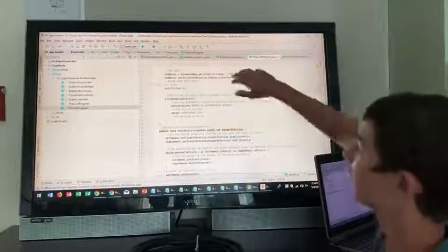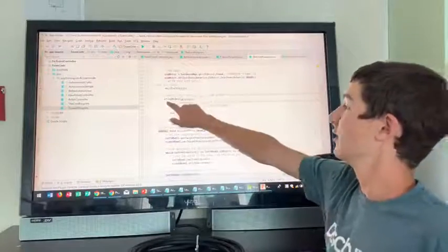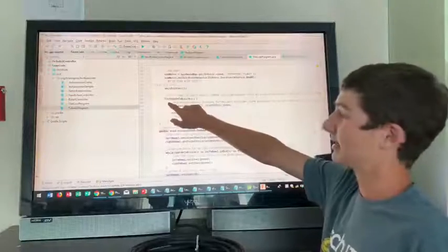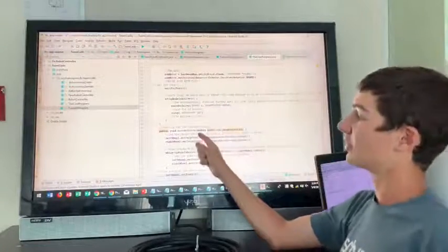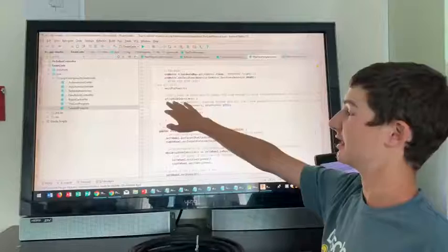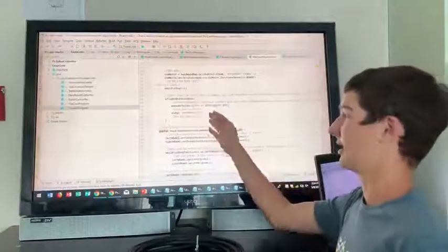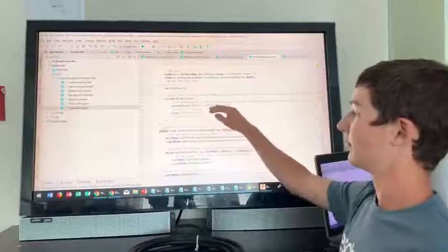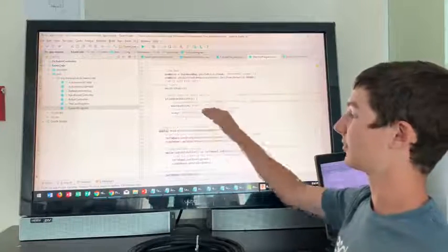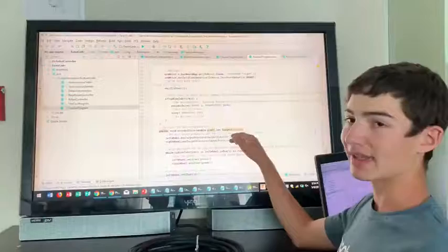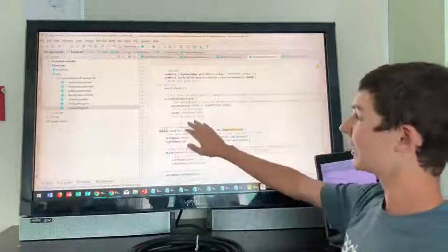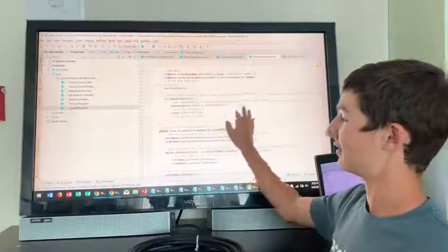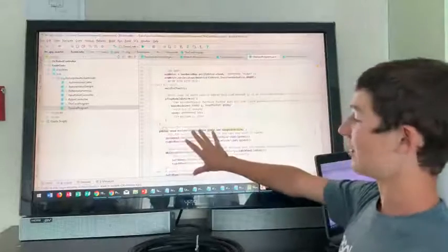And all the way down to our while loop. And actually, we don't have a while loop this time because this is an autonomous program. So, in this program, I'm just using an if op mode is active, because I just want to run through this. It's just going to drive just really short, pause for a little bit of time, and it's done. So a really simple program. And I might add on to that a little more in the demonstration. But here's where all the math happens.